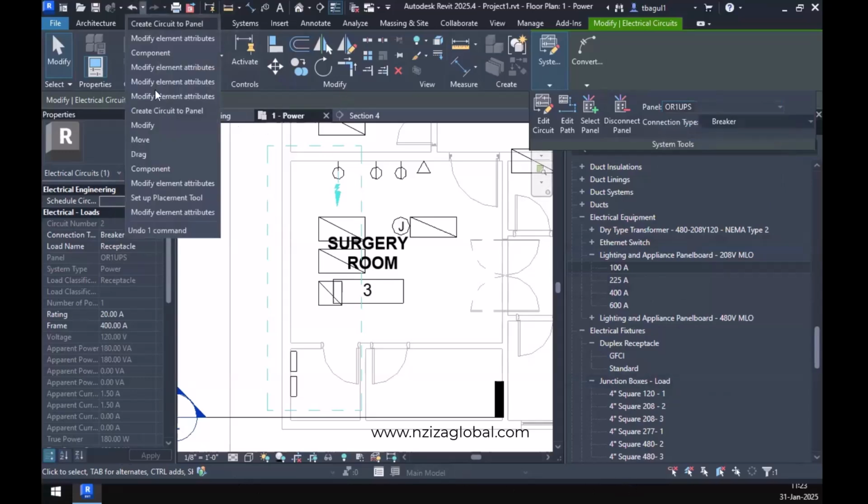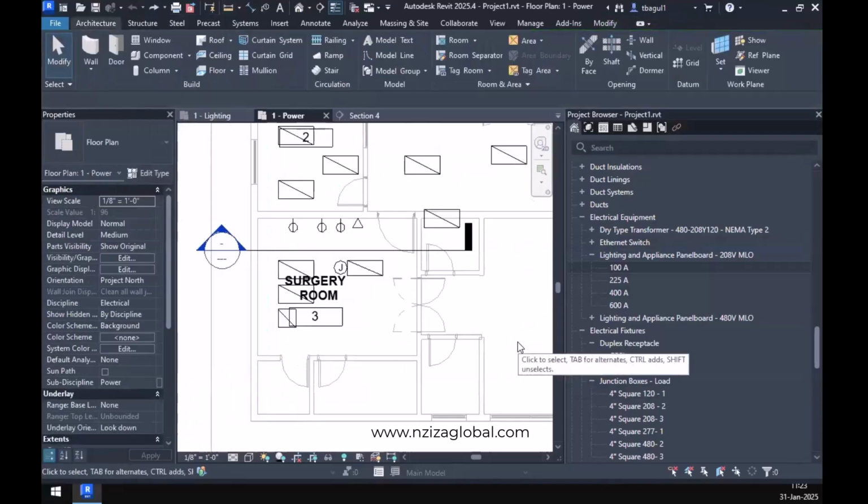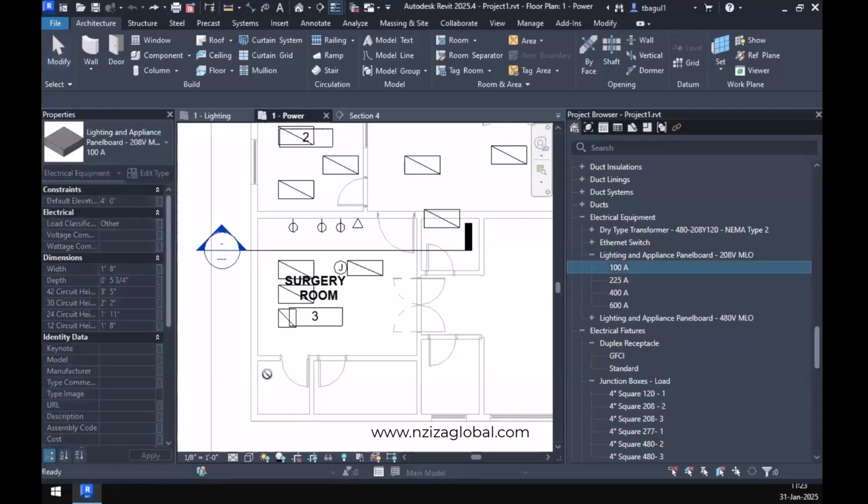So I'll undo everything over here. So there are no panel boards. We'll have 2 panel boards assigned to this operating theater. One will be connected to the utility power. The second will be connected to UPS. It will be all 100 amps, assuming that we have done all the calculation. With the connected load into diversity equals the demand load for the utility panel. For the UPS panel, connected load equals the demand load, no diversity on that. 100 amps, click, hold, drag and move it.